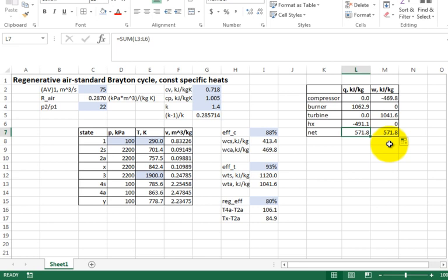Okay. Then I maybe calculate my m dot in kilograms per second. All right, so that's going to be my volumetric flow rate divided by my specific volume at state 1. And there's my mass flow rate, that many kilograms per second. I'll leave all those digits, it's just needed. All right.